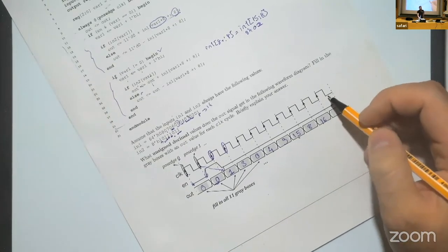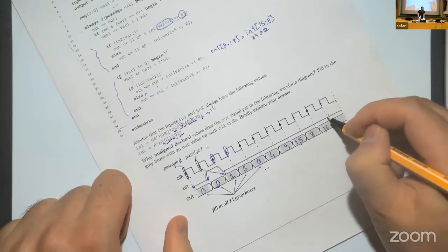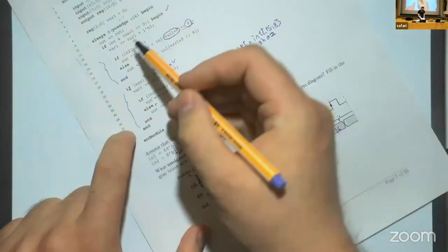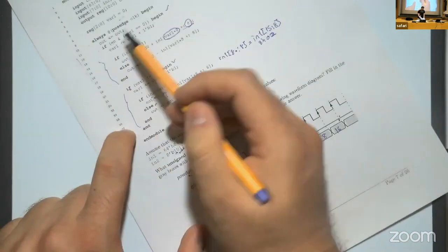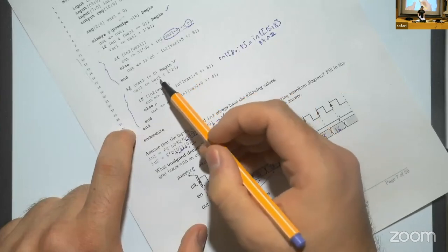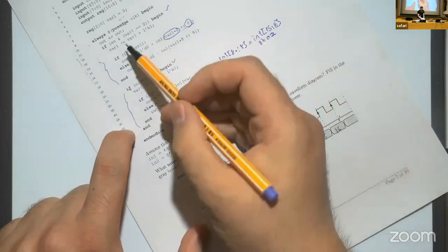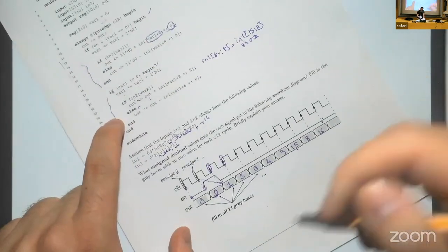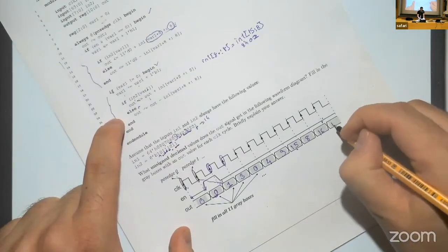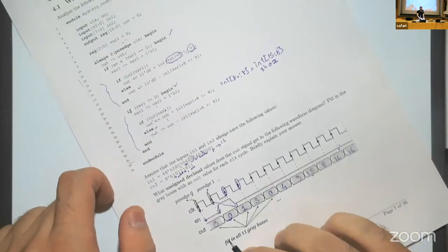Now, in the last cycle, we know that var1 is 0, and you see that enable is also 0. Enable is 0, so we don't go into that block. And var1 is also 0, so we don't execute that block. It's the same as the first cycle. So the output will keep the same value as the last cycle, which is 16. So that's the first question.